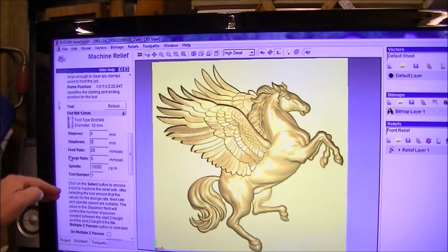Now this is the millimeters per second of cutting speed. My particular machine will cut quite happily at 80mm per second. That's only because I have upgraded the drivers for the stepper motors themselves, and the ball screws. The standard machine would not come anywhere near it. It probably wouldn't even do 50mm a second.